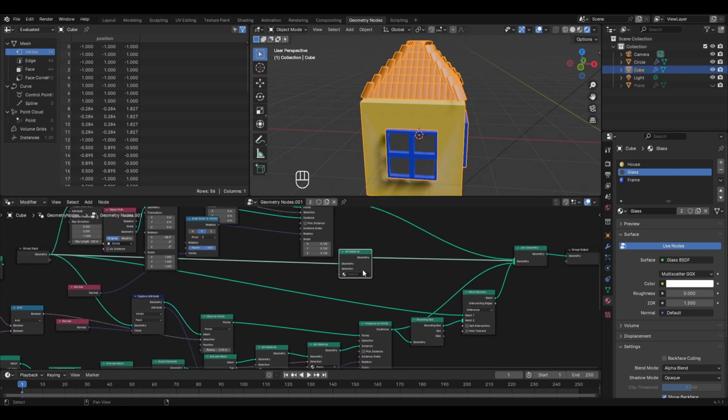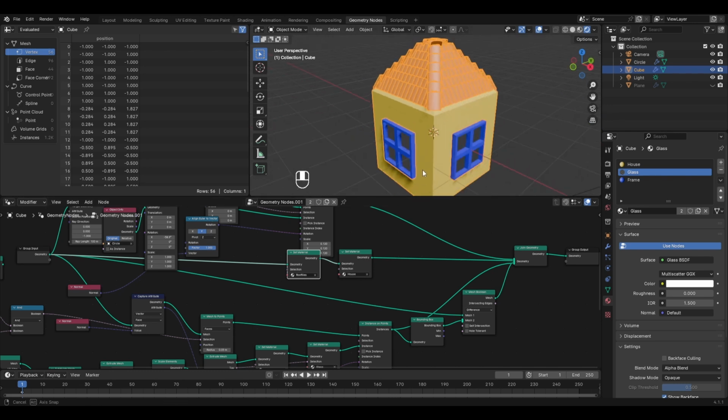Let's zoom in and we'll change the material to house. Then I'll create a duplicate of it by pressing Shift plus D and placing it over here, and change this material to the roof tiles. But as I told you earlier, the one that is present on the right hand side will only be seen as the result. But in order to apply this house material only to the side faces, then for this we